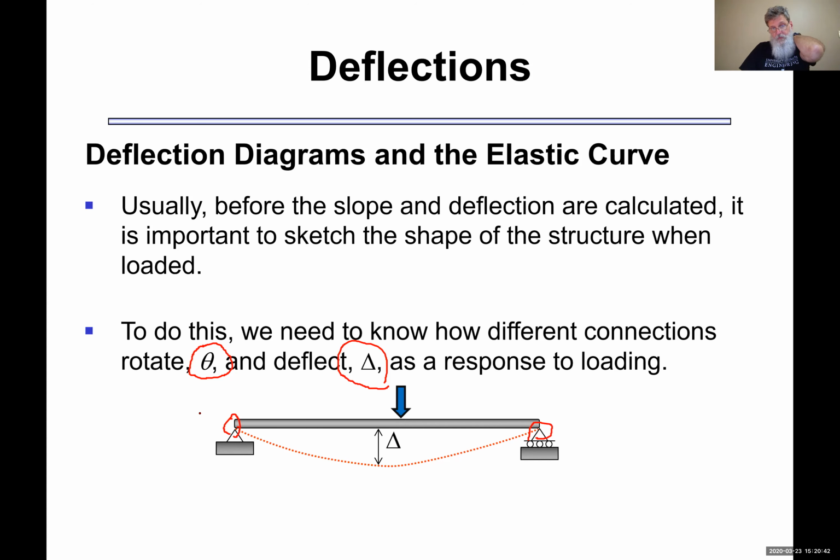And you'll also notice, if I know that deflected shape, that we can know the slope. In this case, here is the slope on the left side at the pin, which I call theta 1, and then there's a different slope over on the right side at the roller, theta 2. You'll notice that on the left side, the slope is negative, gets increasingly smaller till about right here, where the slope is 0, and then it proceeds up positive. So 0 slope indicates that the curve has gone flat, and we all know that horizontal or flat parts of our curve indicate a maximum or a minimum.